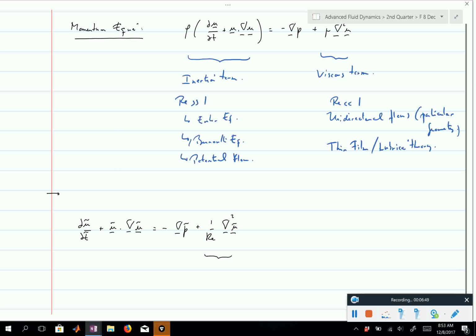And once there is enormous shear, there will be something for viscosity to act on, even if the viscosity is small. Right? So the Kutta condition is, in a way, a consequence of the fact that there is viscosity, even at high Reynolds number. And any time you see vorticity in your flow, even if you model the rest of the flow as inviscid, then in a way you're neglecting something which really is physically in your system. Okay, so let me just write that.